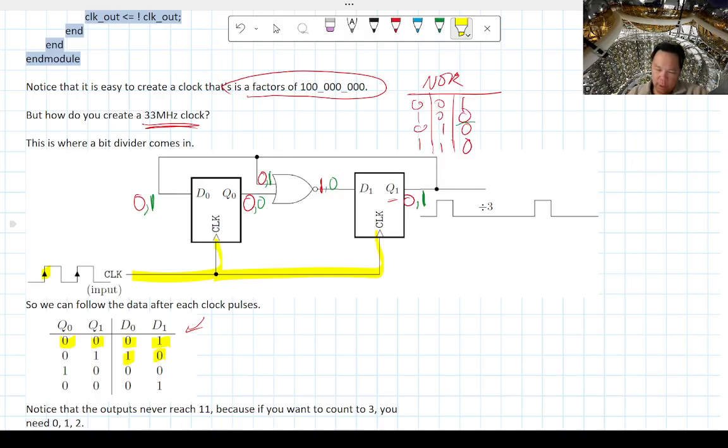Okay, so just as before, right, when the clock pulses from low to high, let's do that in blue now, right, it sends whatever is at D over to Q. So this gets sent to, since this D is 1, it goes to 1 here, the 1 goes here. And then since this is 0, this goes to 0. So now the output here goes low. This propagates back to here, right? This goes to 0, this goes to 0 because these are hardwired, right?